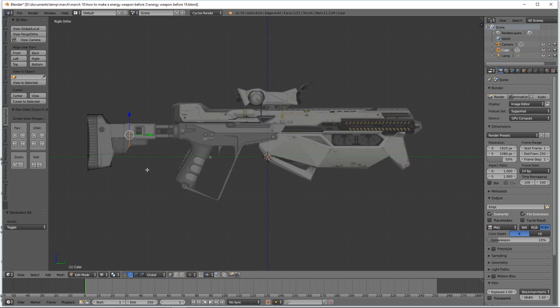I'm then going to press E to extrude, and we have our extrusion line right there. It looks totally straight. So we can either use that, or we can press Y to make sure it's totally straight. Either or is fine. So with that extrusion line, we're going to drag these 4 vertices out to here. I'm then going to left click to lock that extrusion in. I'm then going to press A to deselect.